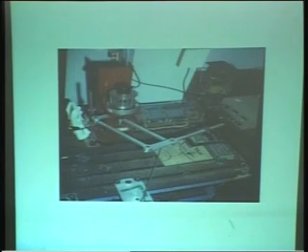Here I am showing you what is known as a pancake motor. You can see the motor driving a special high-speed robot mechanism built in the robotics laboratory here. And you can see on the top there is a motor. That's a very thin motor. The black box on top is the tachometer. A tachometer essentially senses the velocity. Below that there is the motor. The tachometer is standing on 3 pillars. That's why you see the gap between the tachometer and the motor. The motor is below. It's a pancake motor. It's a very thin motor.